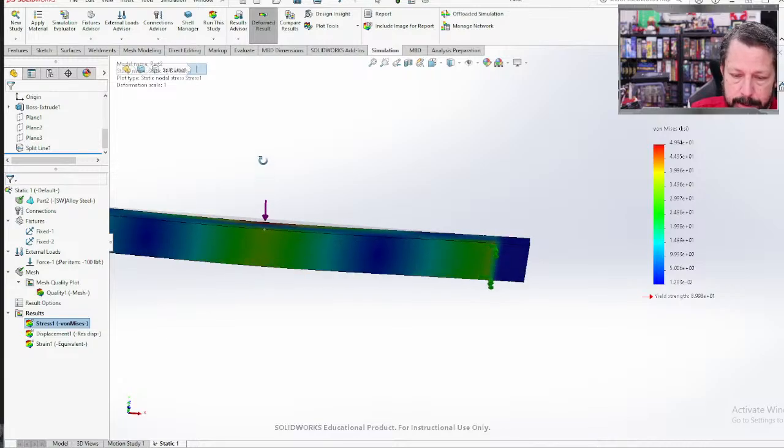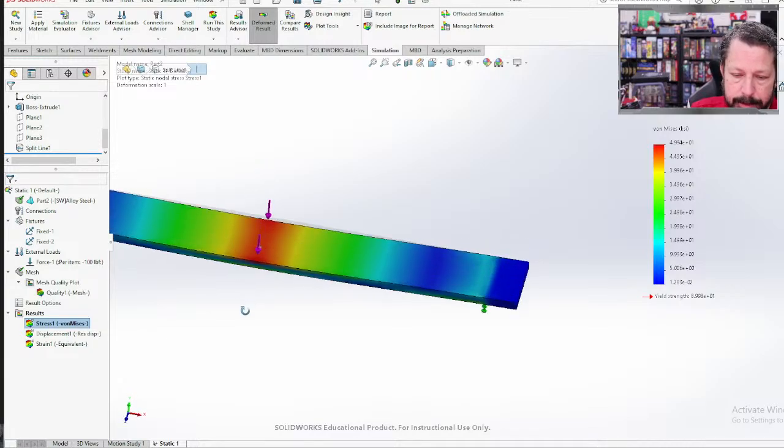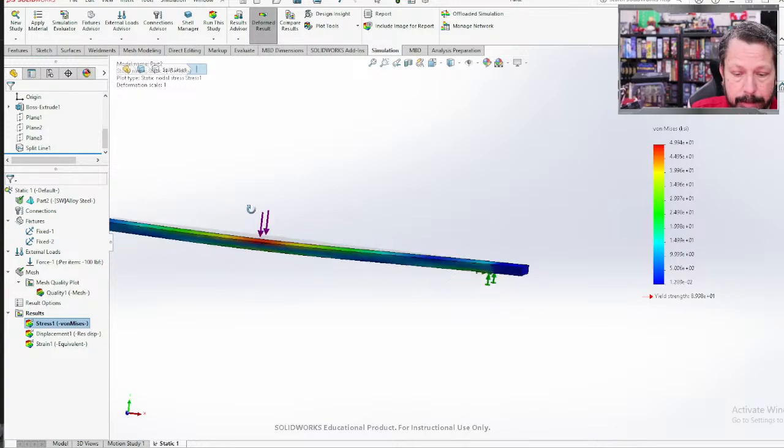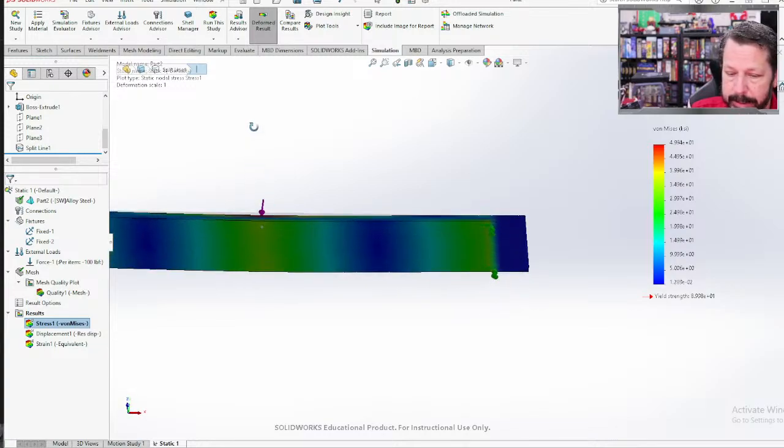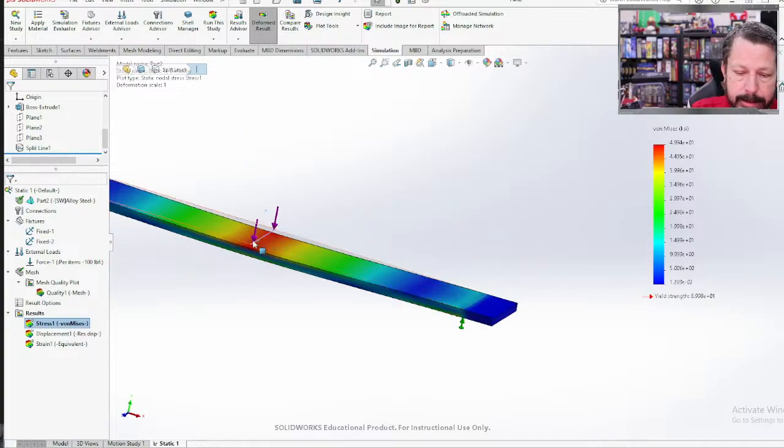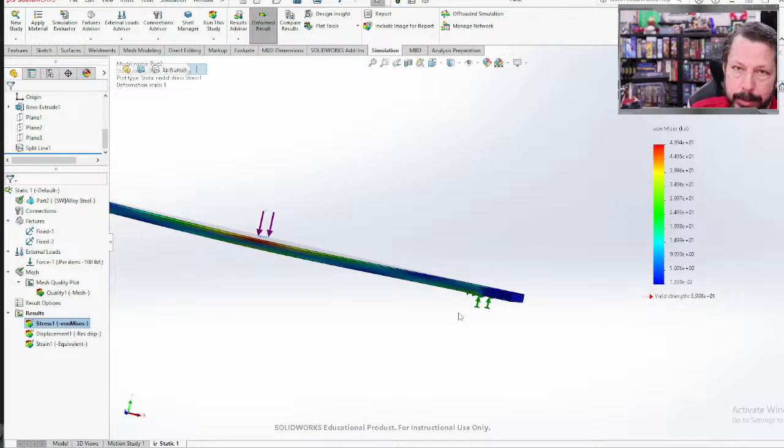I would assume that's probably, in fact, look, there's red on top and bottom is relatively low, and that's not like a negative and positive thing, it's just a magnitude thing. And so it is that the compressive stresses on top of the beam are being a little bit counteracted by locking the beam down and putting everything in tension.